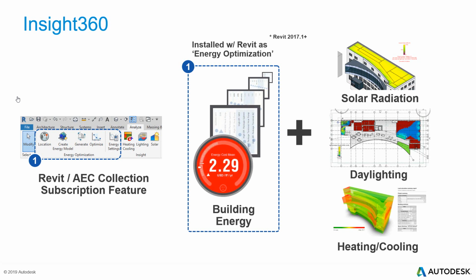So, for example, if you are working on different conceptual stages of your building, of your design, it can give you a very useful idea, like, for example, that building type A with this geometry is performing better than building type B with the other geometry. This can be used very effectively as a comparison tool.